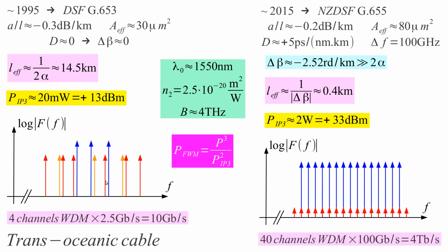In fact, for these old cables, the selection of the individual 4 wavelengths, 4 channels, was very critical in order to have the most of this interference out of the band of these channels. And with 4 channels was already difficult. With 8 channels it was impossible.